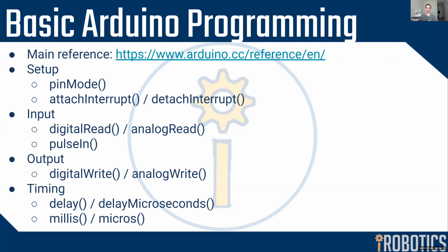As soon as the pin goes high, count up. And then once it goes low again, you're ready to count the next ball or something like that. So you can do that all with interrupts, using attach interrupt or detach interrupt to start watching for the interrupt and to stop watching for the interrupt. So like stop watching for the balls coming or start watching for the balls coming, whatever you'd want that to be. And this can apply to pretty much anything you'd want, not just a color sensor.